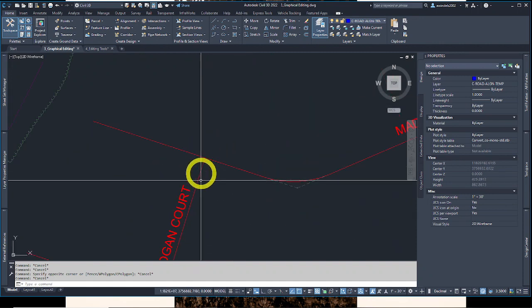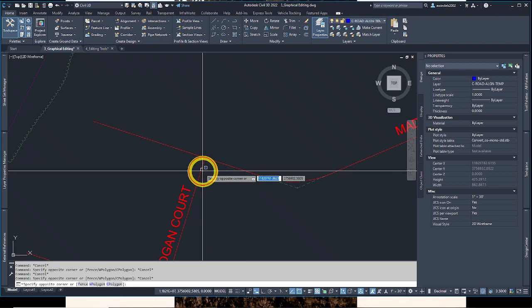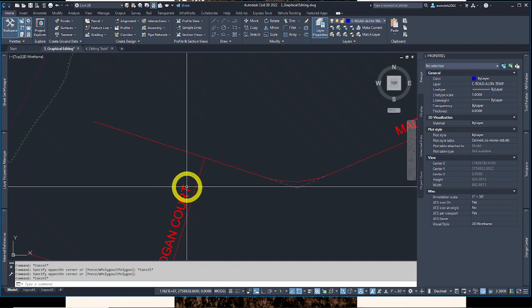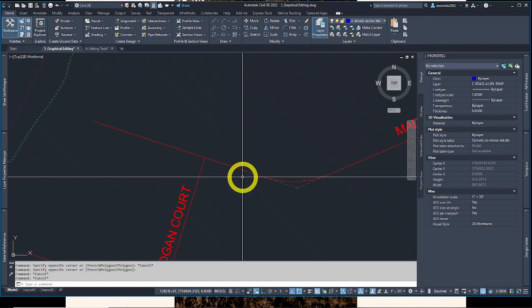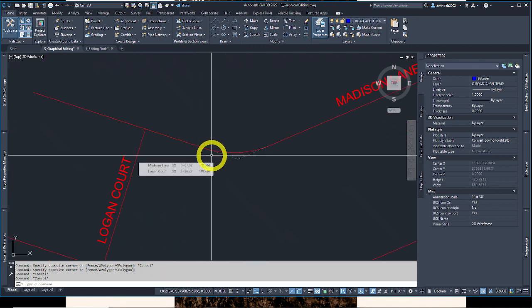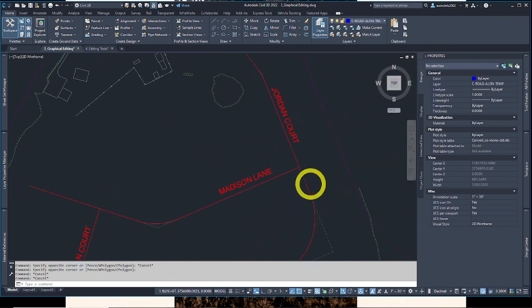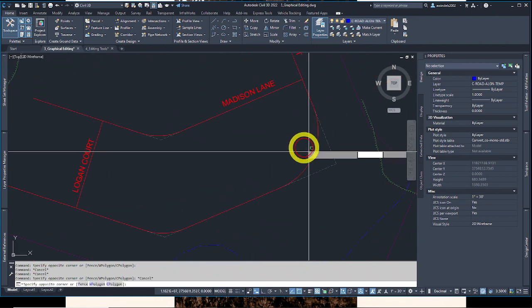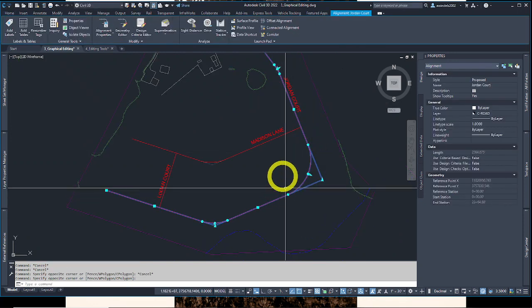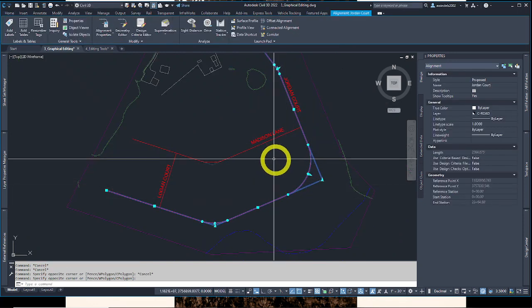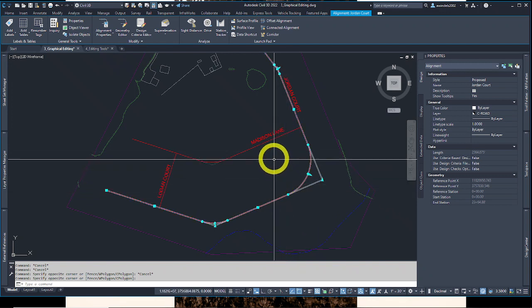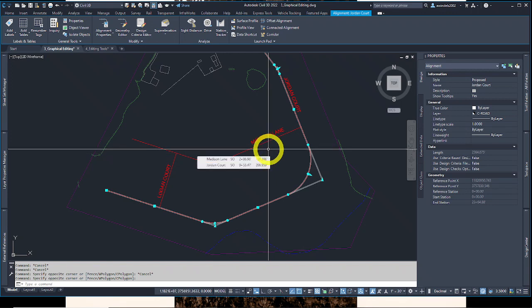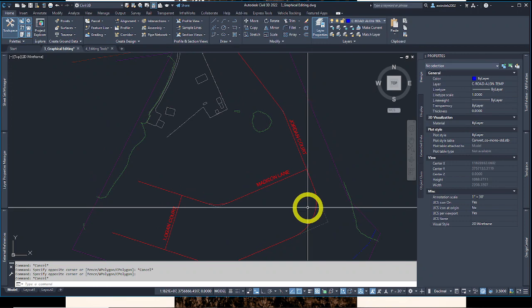You know, perpendicular alignment to an alignment is ideal in a lot of ways for an intersection road, for safety, for people to be visible when they're turning, and accessibility for easy turns. Uniform geometry, especially the 90-degree angles, is simpler and more effective to stake out and construct. So this construction here, this curve with a 90-degree to its tangent. This is a perfect tangent from the center, from this point straight to this arc's or curve center point is 90 degrees. They're easier to construct, so there's a lot that goes into it.